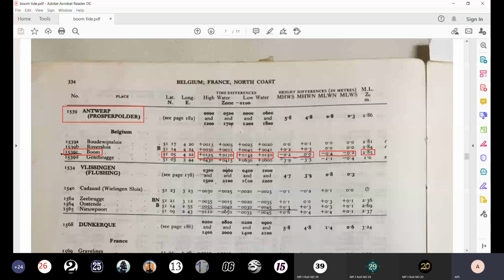So low water is at 1357. So again, convert 1357 will come between 1200 and 1800. So 1200 so much, 1800 so much, 1357, what value you are getting. So see if you are getting 1 hour 53 minutes approximately. Yes, sir. 0153 plus 1357. So then that next low water time will become 1550. Yes, sir. So we just wait for others to catch up. Meantime, you can do for high water.